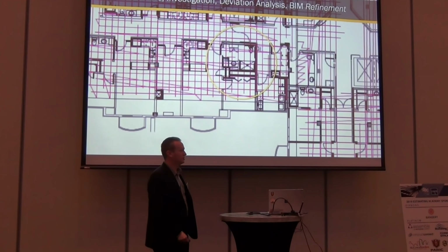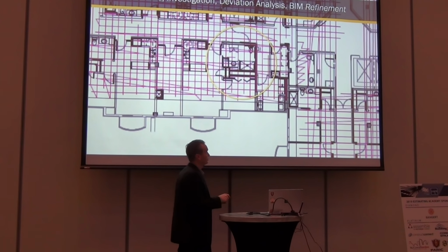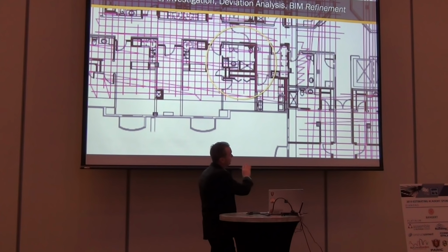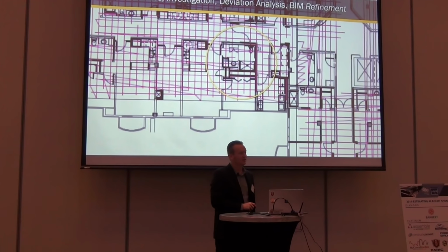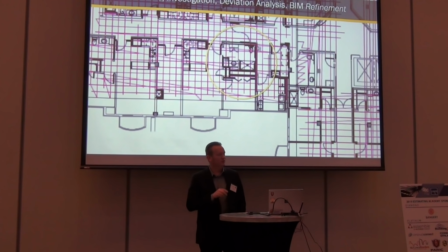So this took us a little time. We were new to x-ray, but we x-rayed every floor of this building, every square foot of the building we had to scan, so we knew where the PT cables were. Because every floor was different. Even if you strand it perfectly, when you pour the concrete, they move.